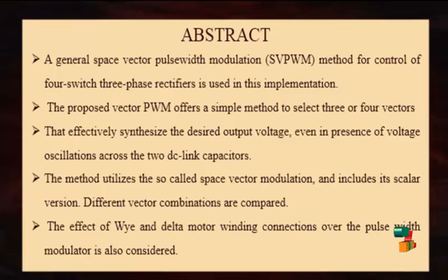3-phase rectifier. Then a high frequency model for the current ripple analysis is proposed in this implementation, along with the effects of 3 space vector modulation approaches on the AC current ripple and also voltage harmonics. According to the analytical result, the method introducing the small current ripple is selected as the optimized space vector modulation approach.